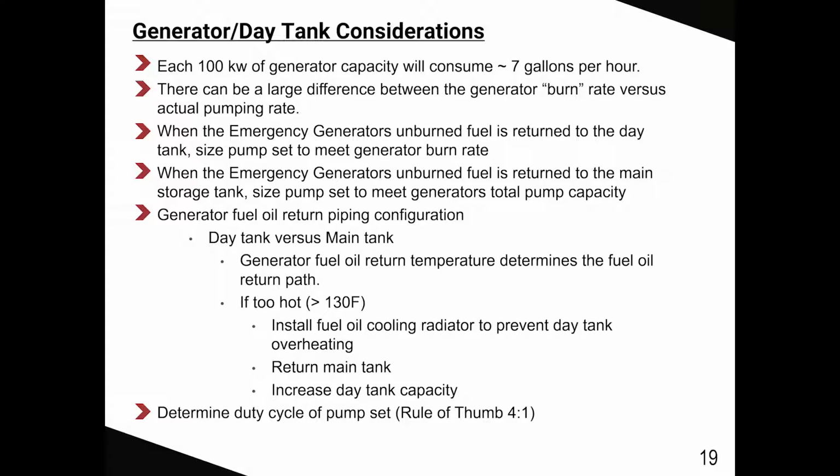Then you determine your duty cycle of the pump set. Typically, on taller buildings, the rule of thumb is 4-to-1. And this could be buildings at 30 stories up. Sometimes with 3 or 4 or 10-story buildings, you may only use a duty factor of 3-to-1.